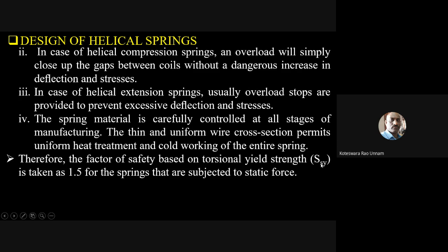It is taken as 1.5 for the springs that are subjected to static forces. When a spring is subjected to a static force, the factor of safety is considered as 1.5. Or not only that, maybe sometimes even less than that also, people will take that based on the given applications.